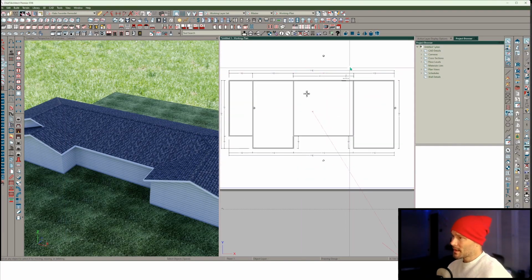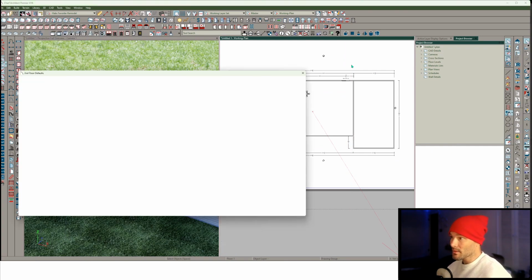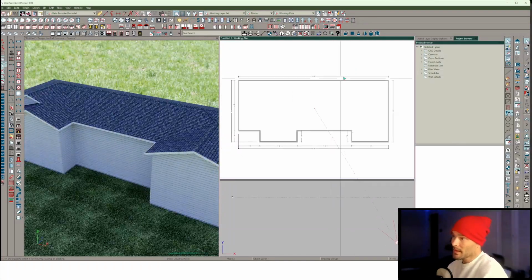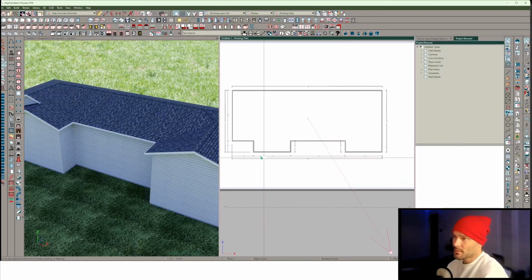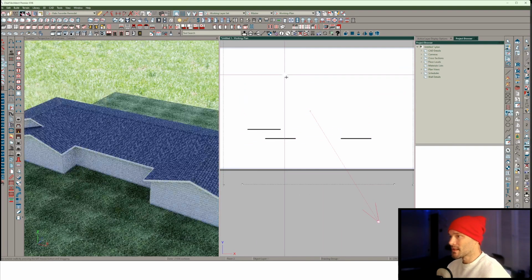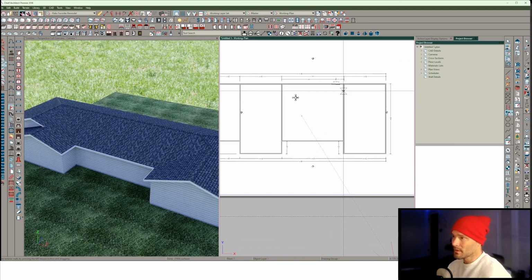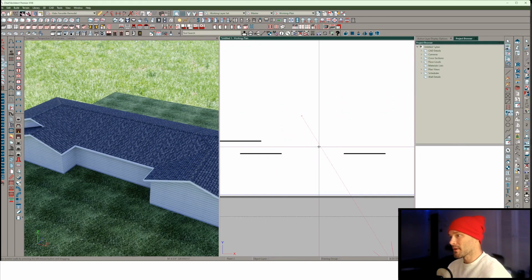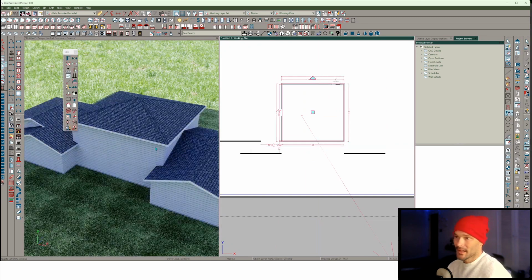So the next thing I need to do, same thing, mnemonic keys, Alt B O, enter, enter, enter will get me a new floor, but I in fact don't want this floor to be the full extent of the building. So if I cycle back through the tools I was just using, I just cycled back to the wall tool to delete these, go down a level, and then since I still have the wall tool, I can shift select these center walls, copy, go up a level, paste, hold position, and you can see here, we're very quickly coming